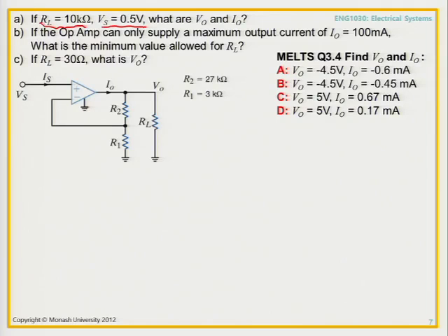Okay, so you can sort of cut this a little bit short because you can see what this is. Yeah? You just did it, right. It's a non-inverting amplifier. So remember what the gain of that is? Equals 1 plus R2 over R1, which is equal to the ratio of V out over V in. Okay, so what we're trying to show here is you've got this non-inverting amplifier, and that's all great. I can now measure the voltage on the output, given I know the voltage on the input, Vs.